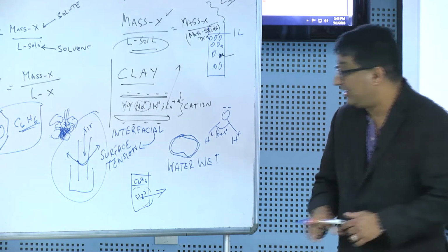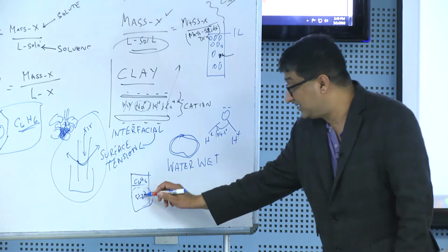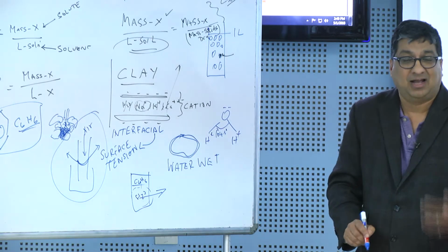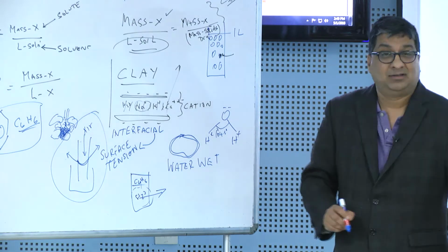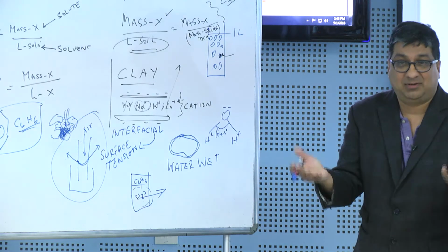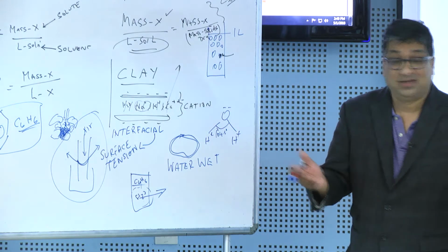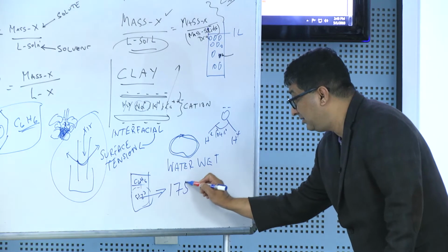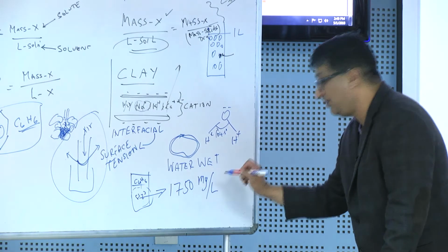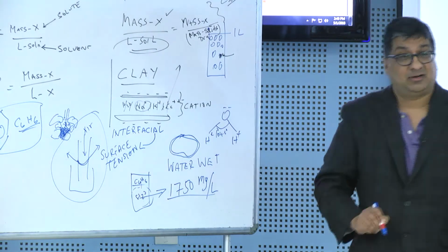Will I find some benzene in there? Yes, because some molecules of the benzene decided to move and get into the water. There will also be some molecules of water that get into benzene, but that's not of interest to me. I'm looking at what's in the water. How much benzene do you think? If I had 1 liter of water, how much benzene do you think I'll have? So that's the solubility of benzene. That depends on temperature, pressure and whatnot, but typically at about 20 degrees Celsius, it will be 1750 milligrams per liter. What do you think the drinking water standard for benzene is?